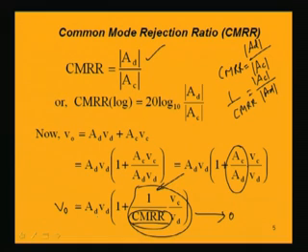So, that is a very significant analysis, because it tells that for a high CMRR op amp, output voltage is basically the difference gain multiplied by the difference in the input voltages. So, the common mode part is almost rejected to 0. That is why we have to have a high CMRR op amp which will be amplifying the output signal based on the difference between the two input signals, and whatever a common part, it is almost equal to 0.